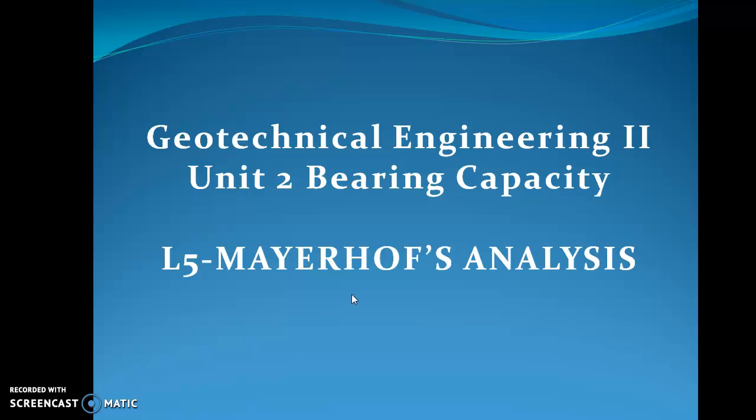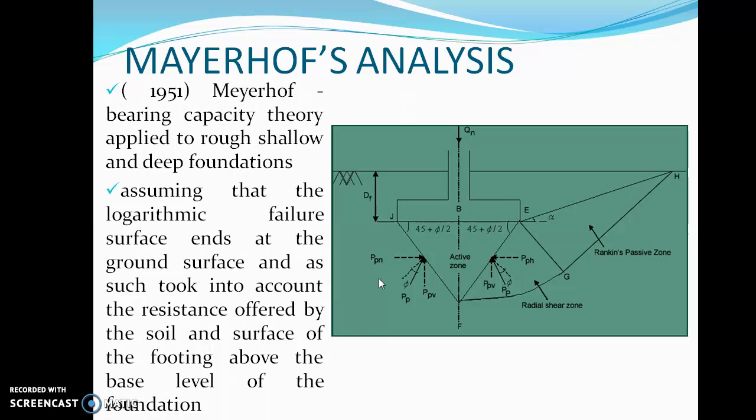Just like Terzaghi's analysis, this is another way to analyze the bearing capacity failure, or failure in the foundation due to insufficient bearing capacity. Now this particular theory was proposed in 1951 by Meyerhof, and this is applied for rough, shallow and deep foundations. So if we try to recollect Terzaghi's analysis, it was not for deep foundations.